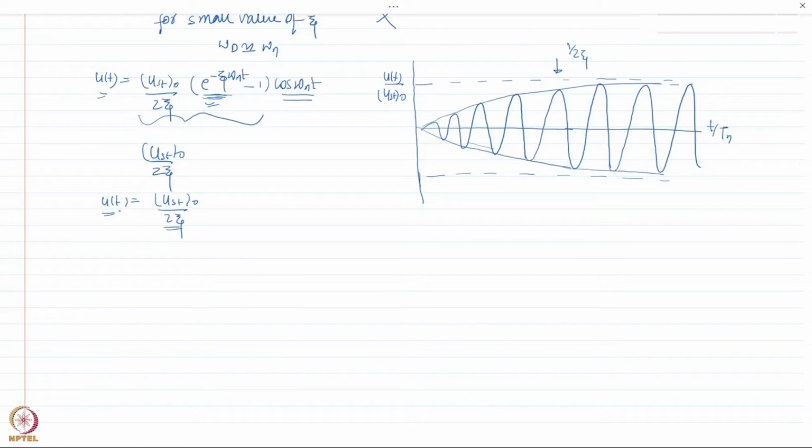To avoid damage to the structure, we include some damping in the structure so that even if there is resonance, my response is still bounded. Now how do we provide damping in the system? There are various ways to do it. People use added damping devices. You could use supplementary damping using viscous dampers. You can use friction dampers.